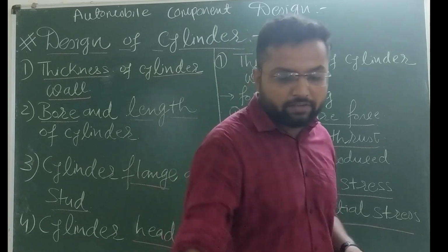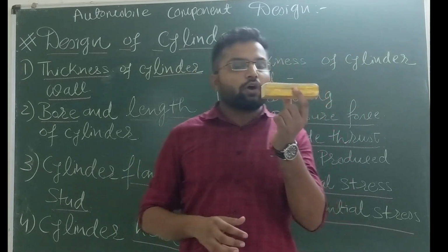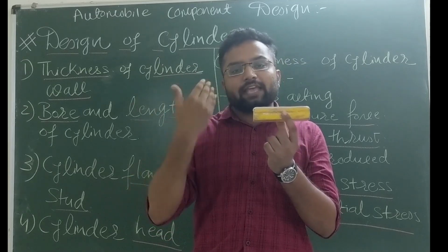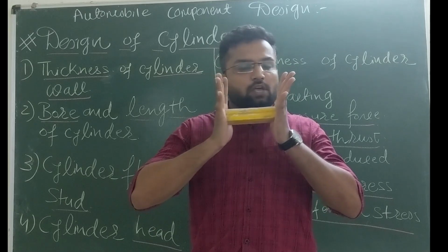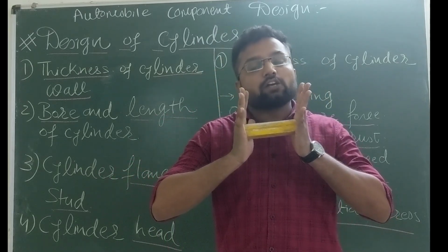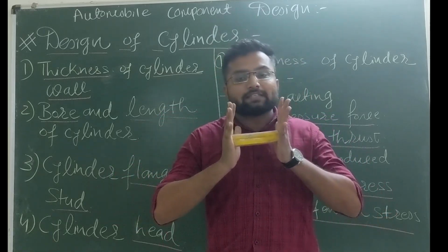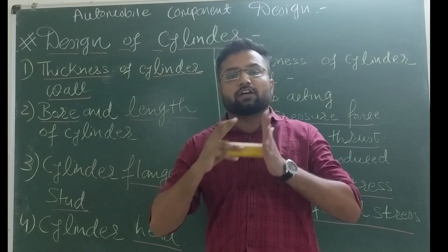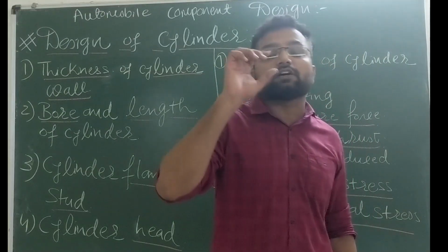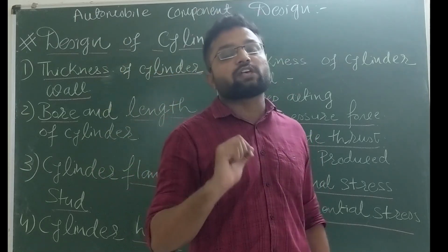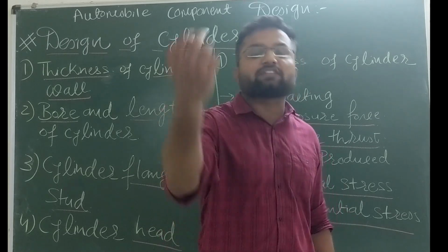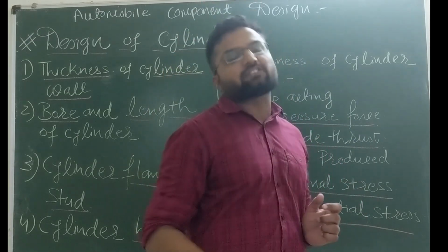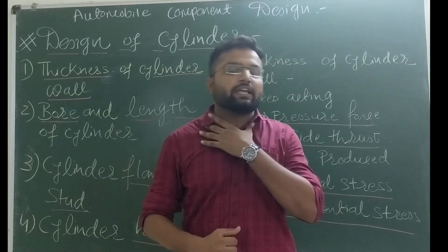If I'm taking this duster, in normal condition, or in isolation, it doesn't come under any kind of stress. But if I put any type of force on it, say a compressive force, it will exert a restriction, or reverse mechanism, or an inherent force to oppose this external force, and this inherent force inside the duster creates stress. So stress is nothing but a reverse mechanism of a body against any external force, and it will ultimately lead to deformation of our component, because when this stress crosses the elastic limit, or plastic deformation limit, it will create deformation in our component.